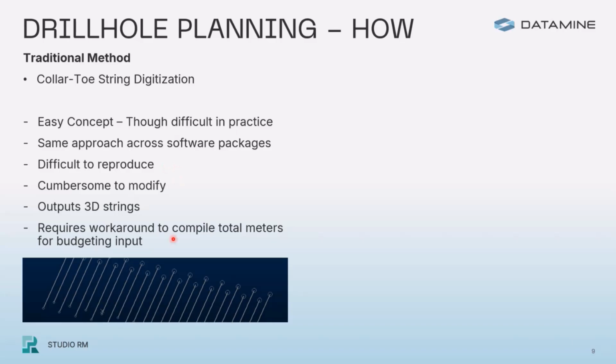And also, with 2D strings, it's stationary and could be cumbersome to modify. It doesn't matter what software packages you're in. And the output is a 3D string rather than a drill hole object. And it does require some workarounds to compile the total meters for budgeting input, like querying in 3D space, that kind of thing.